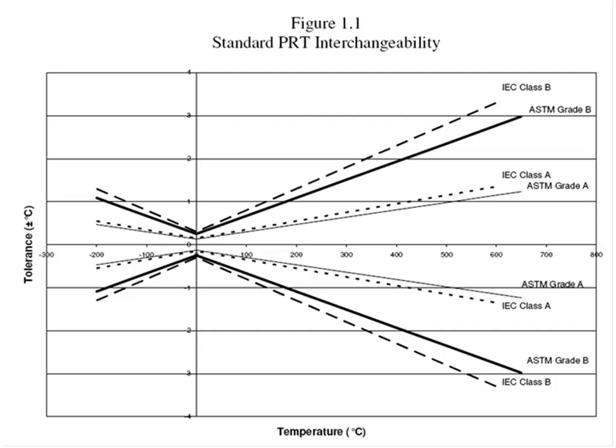Some of the basic sensing elements are manufactured and trimmed to a certain interchangeability tolerance, but then when you build that into a completed sensor, that number can shift just a little bit. And so you need to be aware of that shift by making sure that the manufacturer has measured from the end of the lead wires on the probe. Yeah, thanks, Bill.